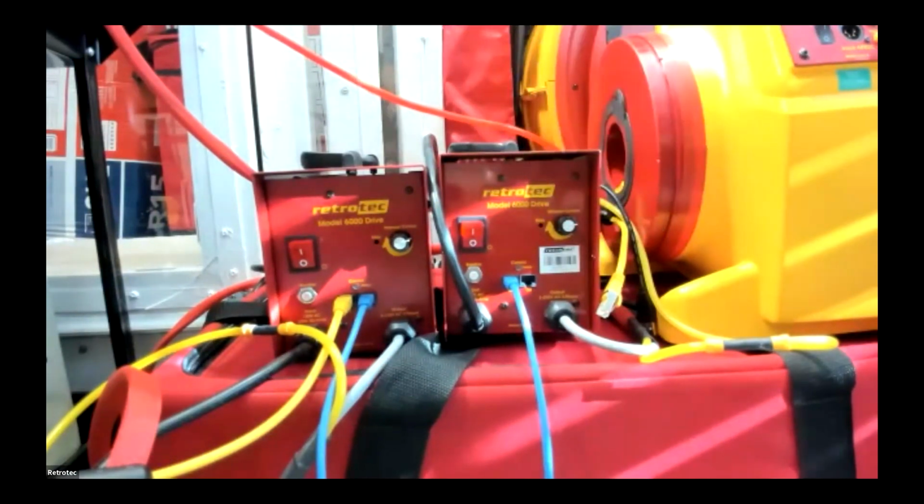The only thing that's connected is the tubing. When you have that first gauge, when you input 50 pascals set and you get your reading, you take the CFM on channel B on gauge 1 and gauge 2 and just add them together. That's your CFM. But if you want to generate a report or do some multi-point testing, then software is where you want to go to generate your reading by hooking up the fan testing.